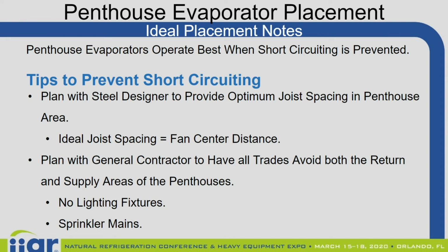So if there was good separation between the discharge and the return on the penthouse, but you obstruct the outlet area of the fans, that can cause short circuiting. If you're blowing down on conduit or sprinkler lines, that can definitely reduce the effectiveness of the penthouse evaporator performance, and it can complicate service.